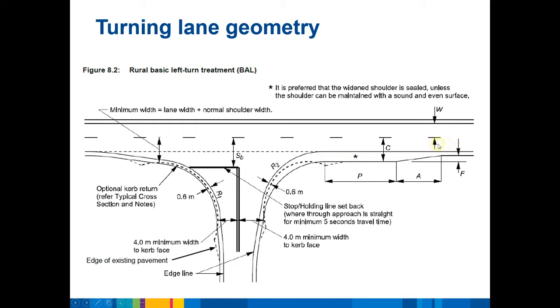You'll probably check your rear vision mirror, and if there's no one behind you, you can make the left turn from the through lane. And if there's someone behind you, or if you know you need to slow down a lot, if you're a truck or something similar, then you'll indicate to get into this lane and then make your movement around. So again, there's lots of geometry. We have particulars on how far back this stop line needs to be positioned. We have definitions on the width at different areas, and this is basically to allow heavy vehicle movements of a consistent manner to get around the corner. And then we have some other geometries here as well, which tell us what the total length of the treatment needs to be.